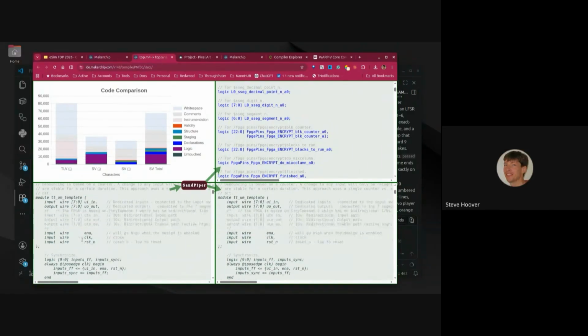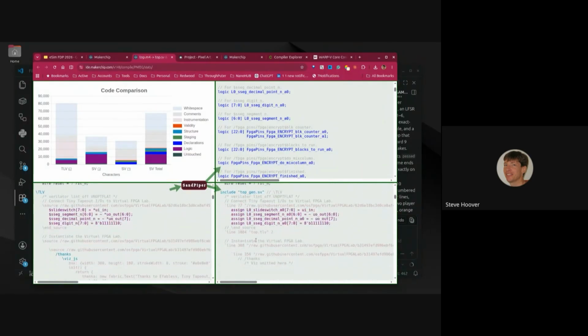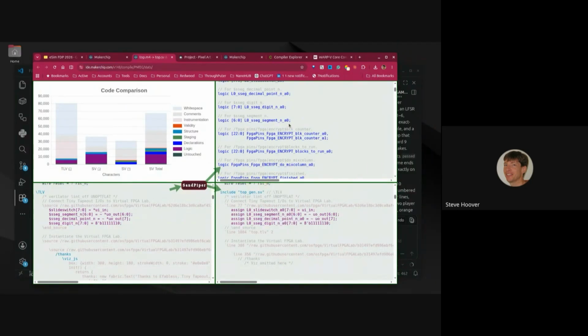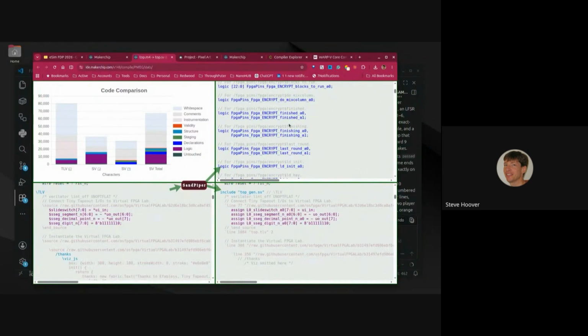The way it's structured, you have your source code, and you have a translated code that's line for line. So you can see the TL-Verilog statements translated directly to Verilog statements. And then you have this separate file that's almost entirely correct by construction. It almost looks like HLS, what happens in HLS with the C++ to Verilog conversion. It's not that at all.